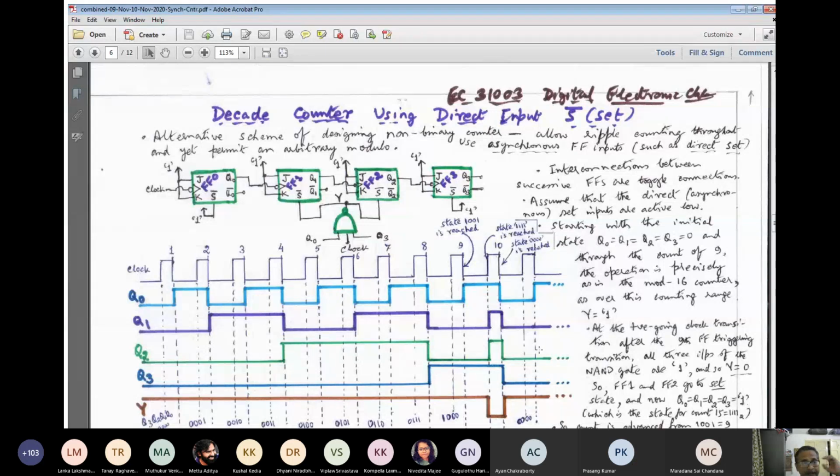The reason is that it is very simple to arrive at the configuration of a ripple counter or asynchronous counter directly by connecting the flip-flop output from the immediately left neighbor to the clock input of the flip-flop. Although there will be some delay, we'll get all the states possible for this 2 to the power n counter.